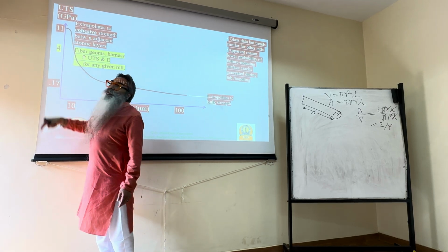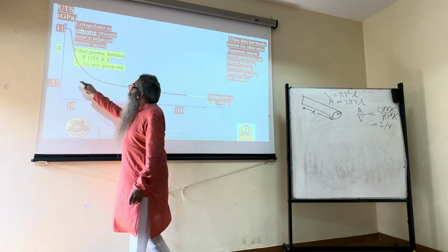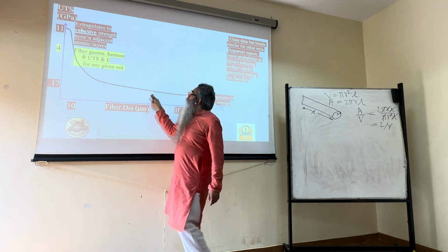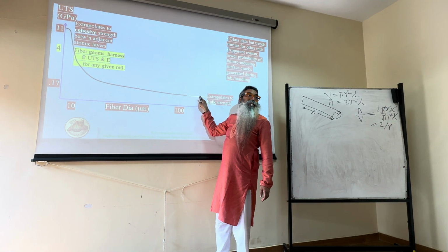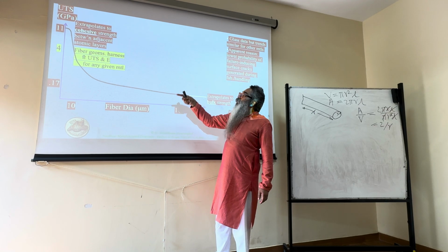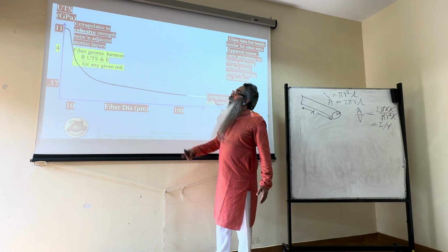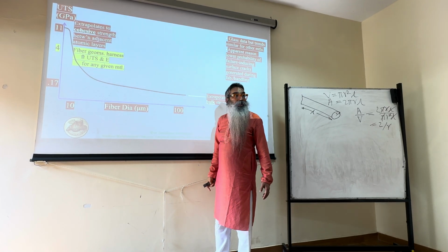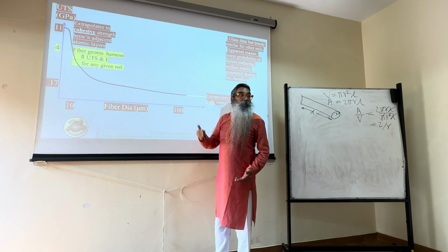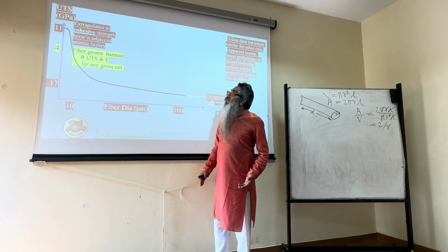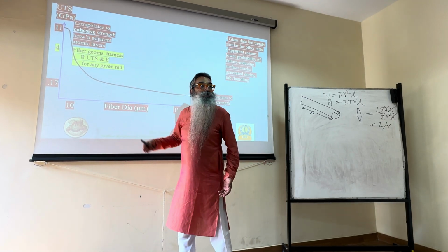You are getting a 4 instead of 11, which is much more than 0.17, which is the bulk strength of glass. Okay, so if you take 4 by 0.17, you see such a large ratio, about 20 times. Or if you take 11 by 0.17, about 60-70 times is what you're looking at. So that's the larger difference that is possible.